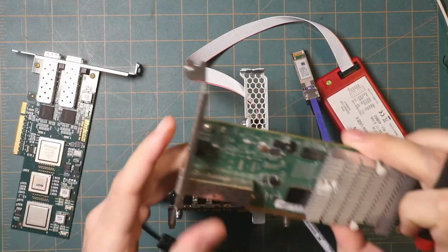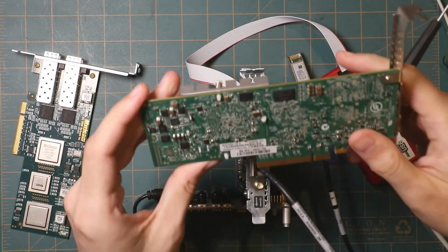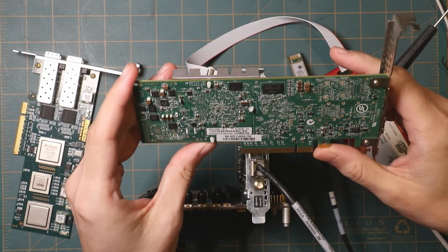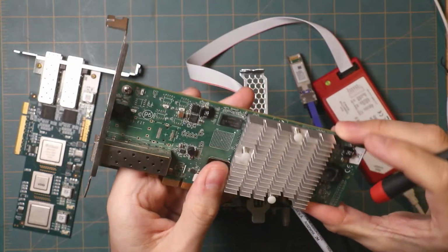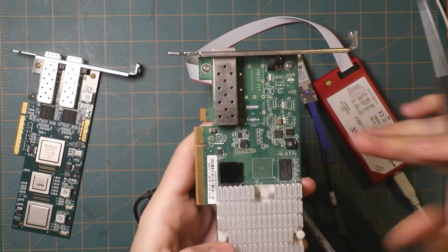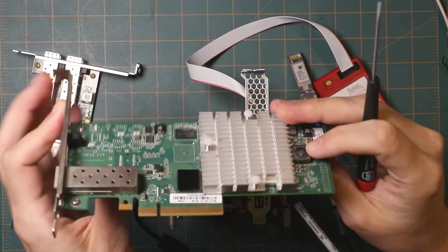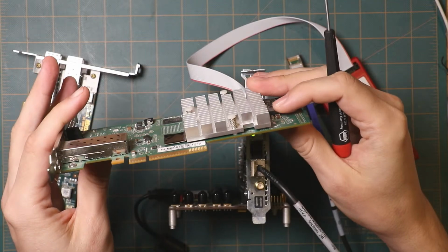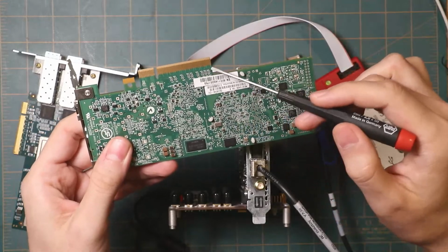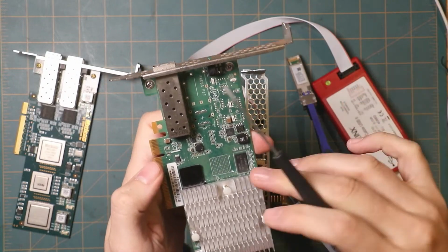And for maybe a slightly different look at the same thing, this is a different NIC that I have. What's the manufacturer of this one? It's a QLE8240. I don't see a manufacturer logo. I think it's a QLogic. This one, it's a single port NIC, but by looking at the board, you can tell that they use the exact same board for the dual port version. In this case, we can actually see the traces that are wired up here. So this one has a single NIC ASIC on here. Might be able to see that under the heatsink. We've got 8 lanes of PCI Express that goes to this guy, and then that's hooked up to the SFP+ modules via a couple of PHY chips.